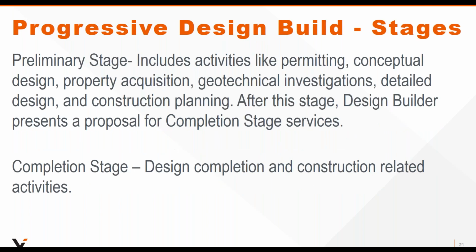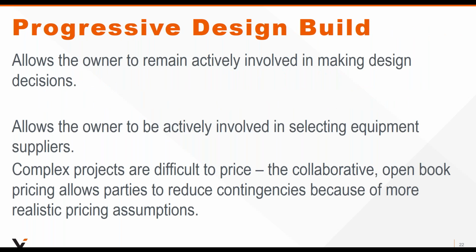During the preliminary stage, there's activities like permitting, conceptual design, property acquisition, geotechnical investigations, and then more detailed design and construction planning. After that preliminary stage is done, the design builder will present a proposal for completion stage services. And during this process, the owners are getting more progressive estimates of what the solution is going to be. And then the completion stage is design completion and construction related activities.